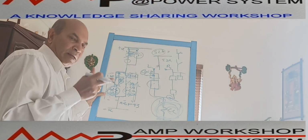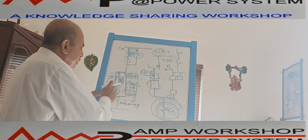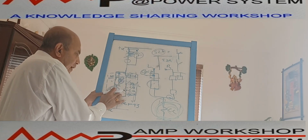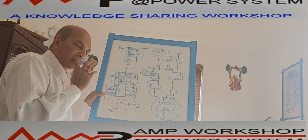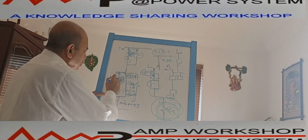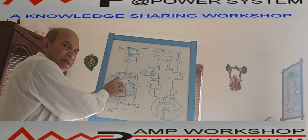Immediately, once it is energized, it is also energized through the 94. So this 94 relay remains energized through two parallel paths. One is the breaker path, the breaker auxiliary NO contact, which becomes NC upon closing the breaker. This is an NO contact, so through the closing of the breaker it gets power, as well as the moment the anti-pumping relay is energized, it is getting power. So in both ways, it remains powered.